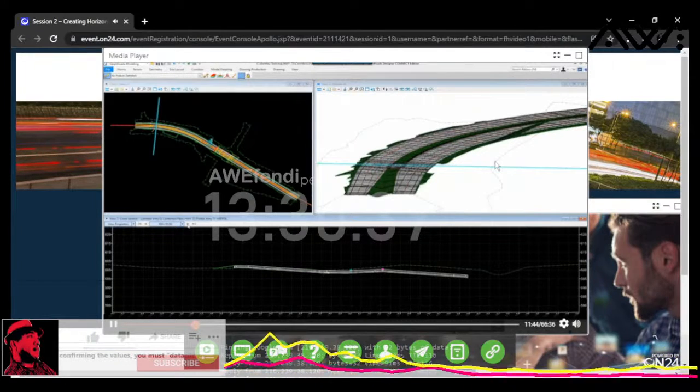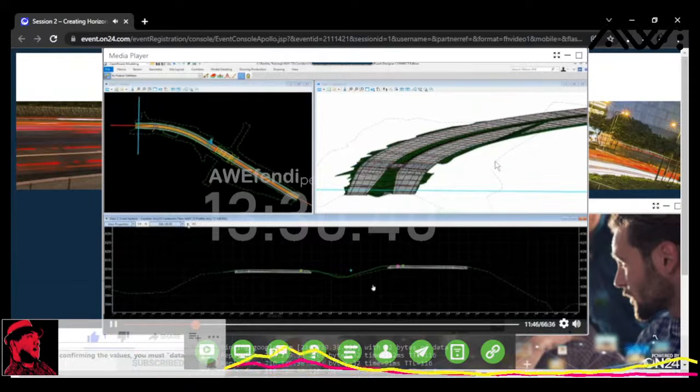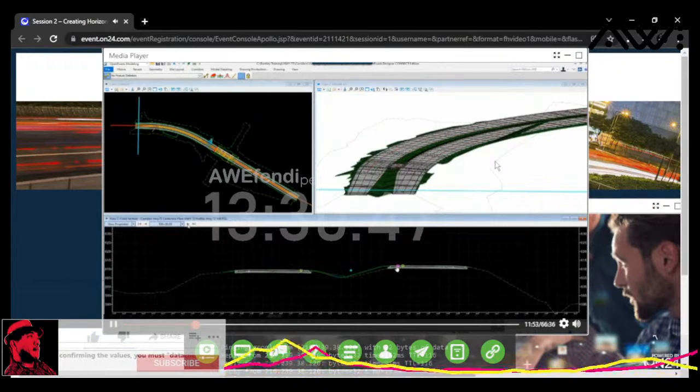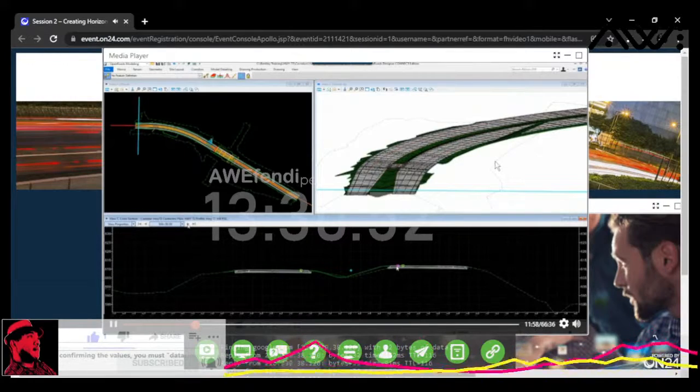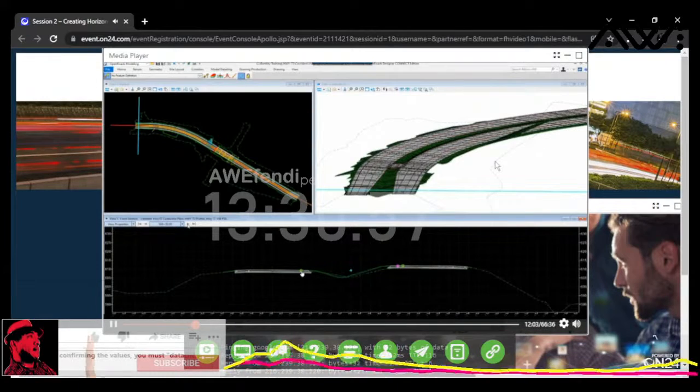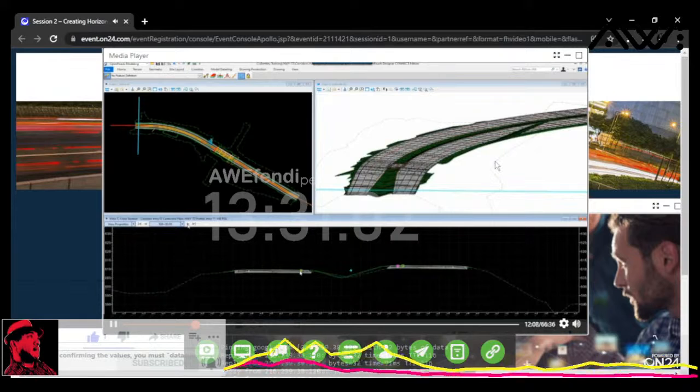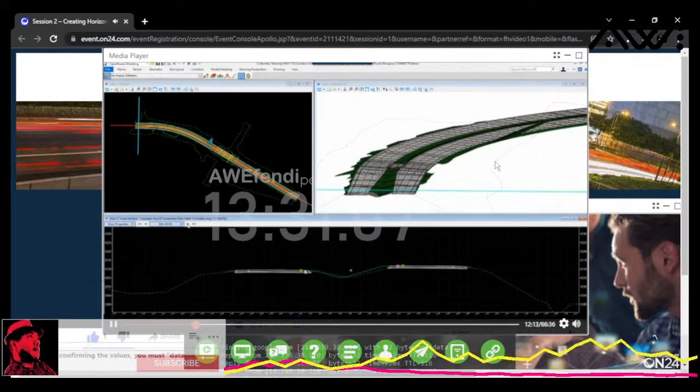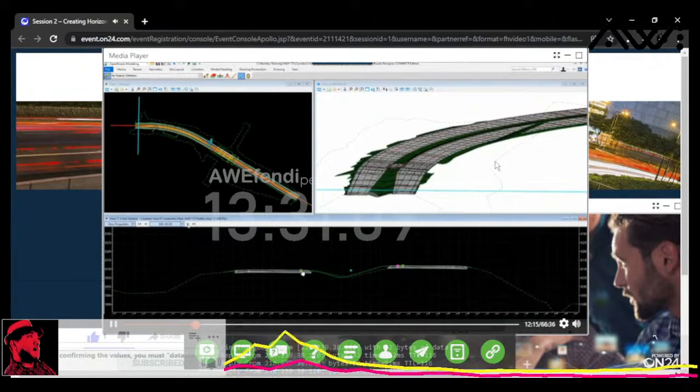Now, if we go back to the beginning of the roadway, as we look into that transition, you'll notice, again, we're going to have to modify the vertical between the eastbound and the westbound sides of the roadway. So we'll have to, again, create that control line vertically. But you'll notice the PGL that we're going to create is in line with the eastbound roadway. The eastbound roadway, we wanted to maintain its current location just for grading outside and right-of-way constraints, as well as driveways, intersections, and some other things along the roadway corridor. So we're holding the eastbound side. We're going to widen to the inside and create a new PGL along that widened pavement, okay?